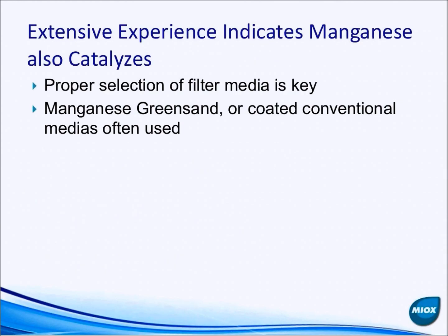Now, as I mentioned, the reaction is normally quite slow. So while iron, for example, can be oxidized fairly quickly, even with something as simple as oxygen, manganese will take hours, if not days, in the presence of something like oxygen. In the presence of something like chlorine, it can take a matter of hours or so, usually 2 to 3 hours if you're literally trying to just simply oxidize and filter and do something really simple like that.